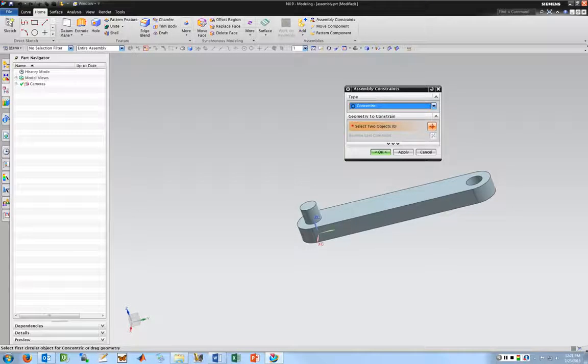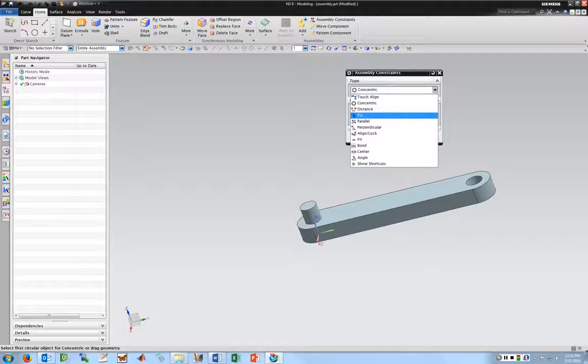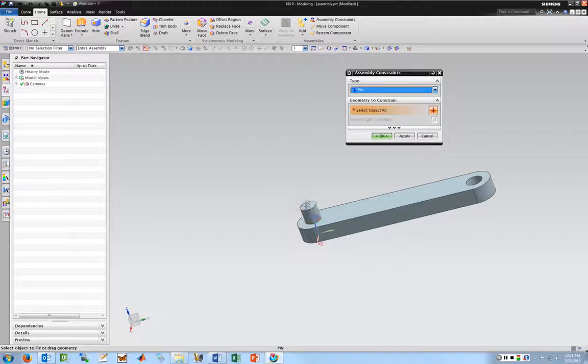So if you want to follow the process I used in the last tutorial, you just add them one at a time. Add the first one, fix it, and then add the next one and use by constraints. Going this way, I definitely need to fix this thing first. Since I use the same coordinates, the XY plane, for drawing both parts in the same origin, they automatically line up. If they don't line up, you're going to have to either move them around to get the constraints to work, or just apply constraints and see what happens. But since they're where I need them to be, I don't need to try to move them. I'm going to go ahead and fix the pin.